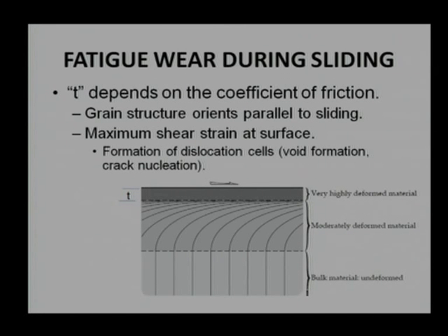then what will happen? At the interface, there will be some void formation, which we have seen a number of times. When you bend rubber material, you are able to see some pores in it; that is void formation. If there is a void, that means there is no material. The area which can sustain stress is negligible, and that layer can be torn away or chipped away easily. Wherever there are too many voids, fracture will occur easily, and that will remove the complete surface.